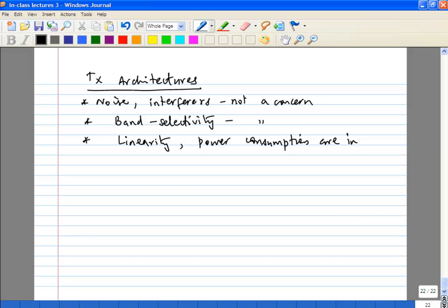Yes. So noise is not a problem. Ultimately, output noise will also get transmitted. At the receiver you are interested in receiving, so the signal values you are receiving are in microvolts, maybe even smaller than microvolts. Here on the other hand, the signal going into your transmitter from the baseband will be in several tens or hundreds of millivolts.